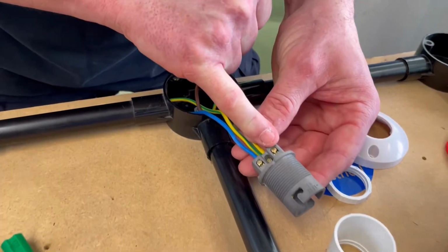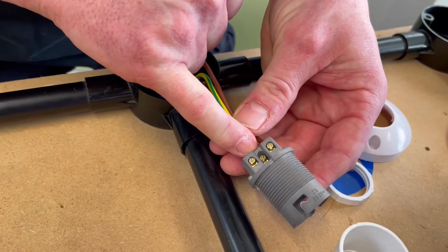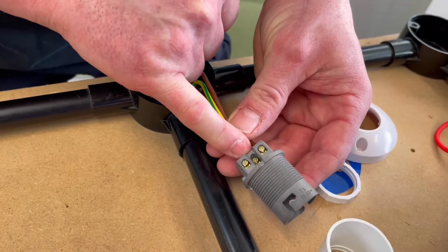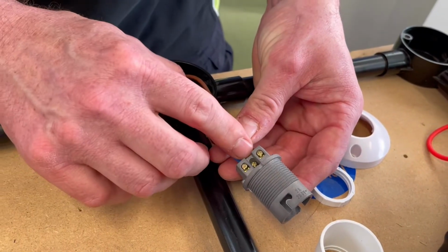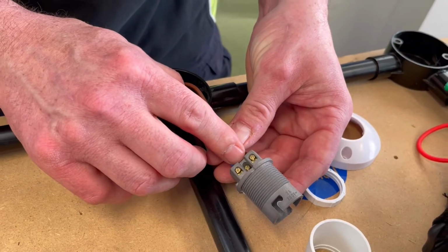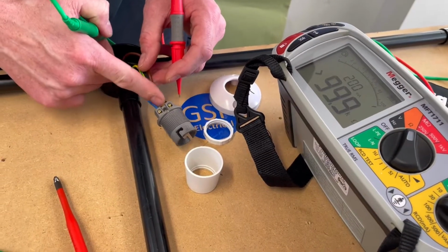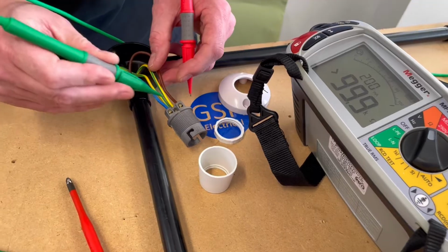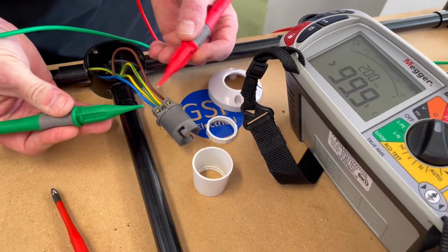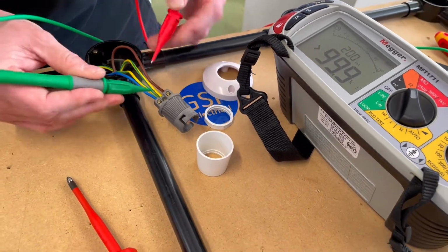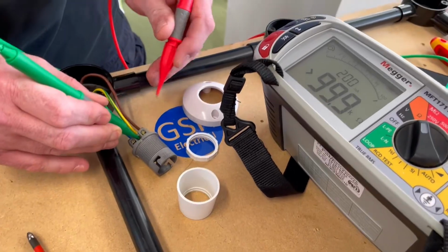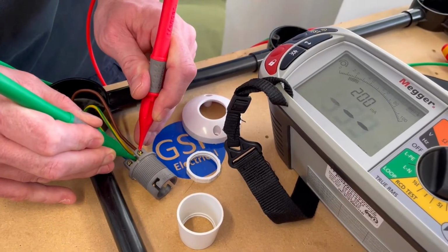So we're going to be testing between our switching line and CPC here. We're going to get a reading in ohms, we're going to operate the switch, and then we're going to see the fact that it will get full scale deflection, and then we'll leave it in the on position next. So I'm going to probe onto my circuit protective conductor and my switching line at the lamp holder. It doesn't matter again which way around our leads go, but again we like the green one to go on the green and yellow one. So onto my circuit protective conductor and onto my switching line.